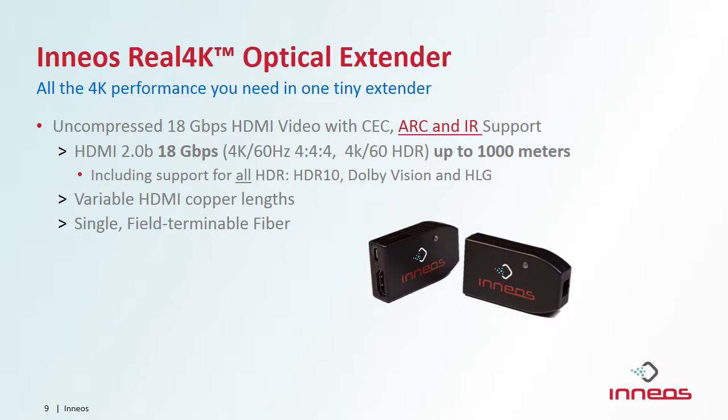The Real 4K optical extender not only supports the full 18 gigabits HDMI over a single fiber, but also adds support for the audio return channel and bidirectional IR control. Again, all over one single fiber. So this allows you to do all of the HDR10, Dolby Vision, whatever cool HDR technology that you have without having to worry about that signal integrity and that video picture being compromised using compression. It also allows you to plug in variable lengths of HDMI copper cable to interface with your source and your sink so that you can have a very clean installation depending on where you want to mount your adapter.